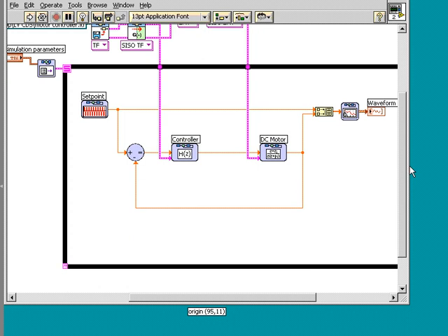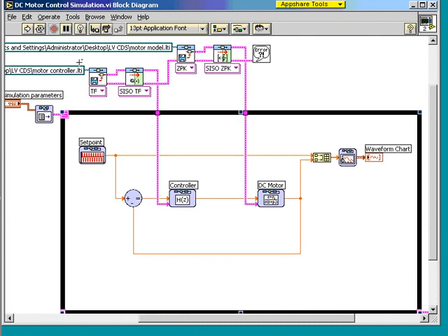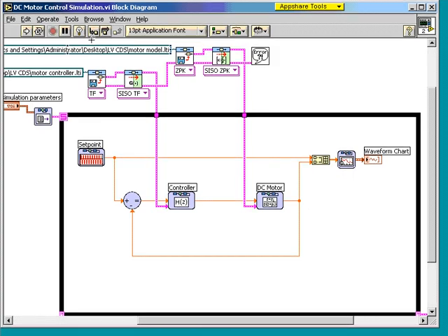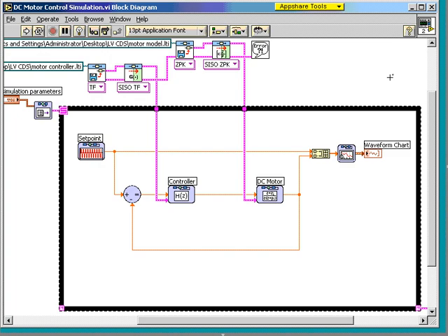We'll take a look at an example now of a LabVIEW VI where we've actually created a LabVIEW simulation that shows the closed-loop simulation. Here I'm using Control Design Toolkit functions to load in my motor model and my controller model. These can then be wired into this structure, which is a LabVIEW simulation loop provided with the LabVIEW simulation module. Within the simulation loop, we actually have the ability to represent control block diagrams directly. In this case, we have arrows on wires, and we have feedback structures directly within the simulation.